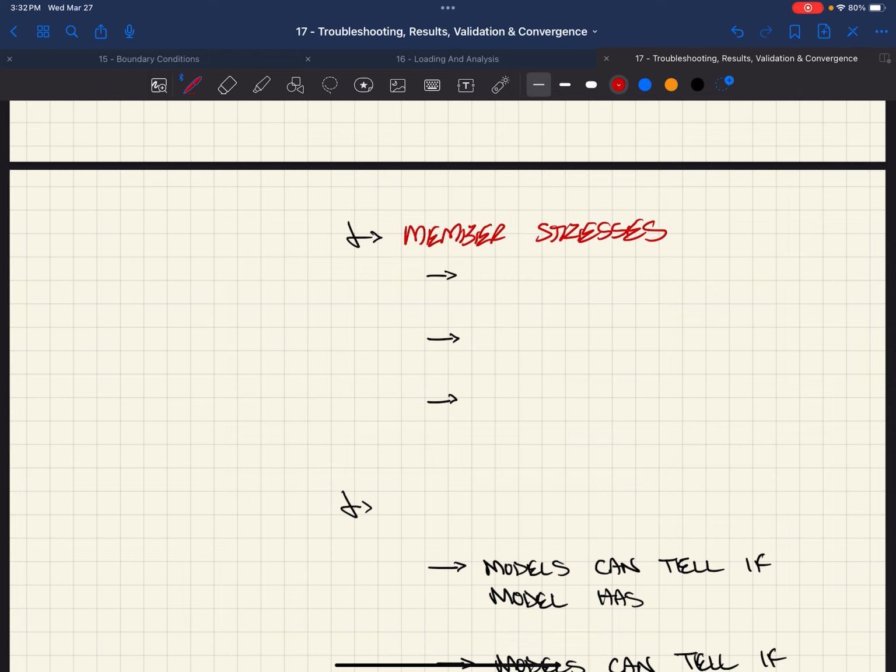It gives us geometry for them, but also we've designated materials, and so those materials give yield and ultimate stresses. And so it can then go through and figure out in post-processing the stresses that are in our elements, and it could say, oh, hey, by the way, this W16 by 26 has exceeded its yield stress.